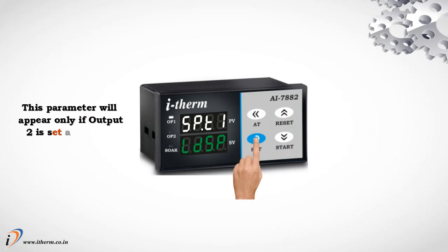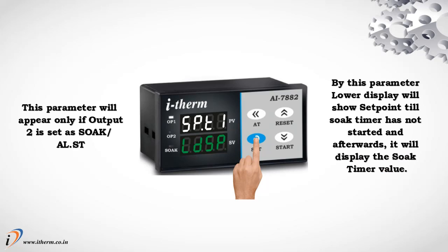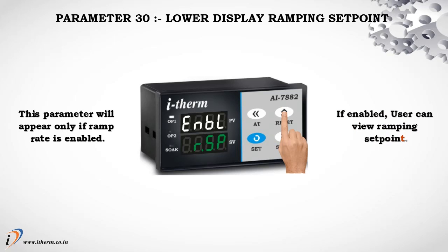This parameter will appear only if output 2 is set as soak, alarm soak time. By this parameter, the lower display will show the set point till the soak timer has started, and afterwards it will display the soak timer value. Parameter 30, lower display ramping set point. This parameter will appear only if ramp rate is enabled.